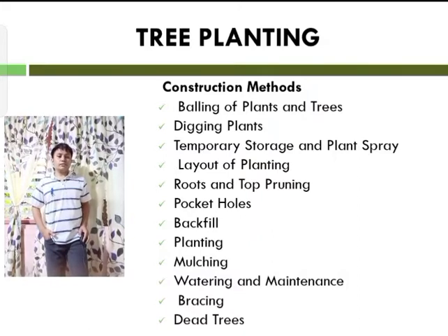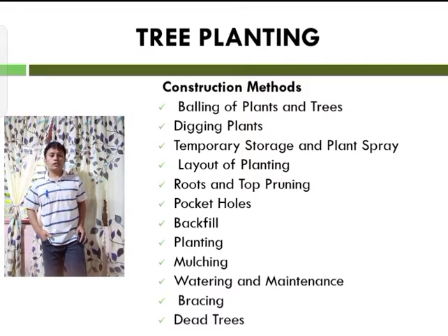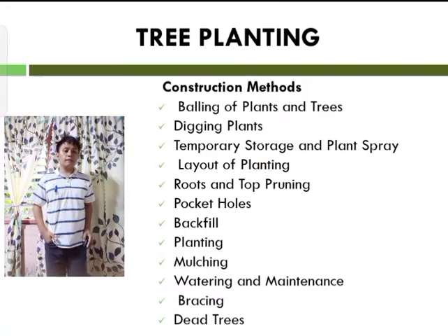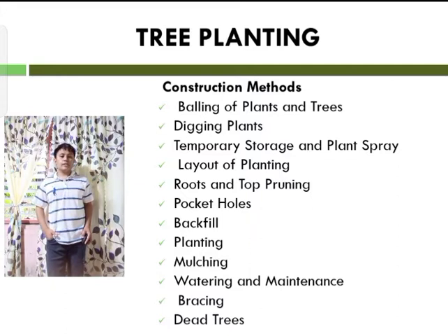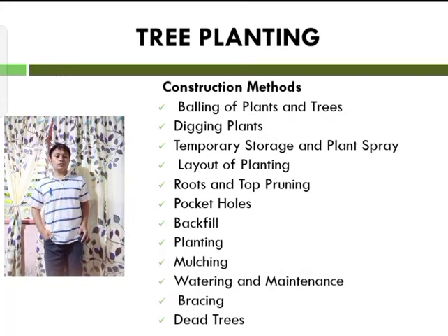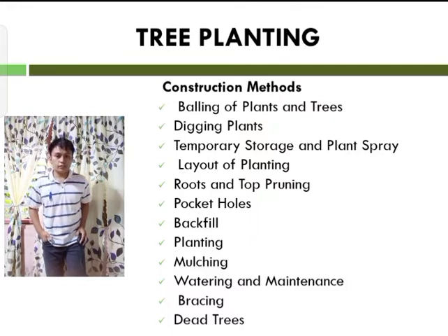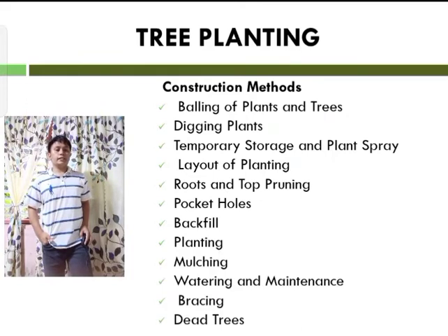So for balling of plants and trees, balling is employed in plants and trees to be transplanted and transferred. To ball out the trees, the depth to which the root system reaches is first determined. So for digging plants, all plants, nursery grown or collected, shall be dug with care and skill immediately before shipping, avoiding all possible injury to the plants, loss or damage of roots, with particular attention being given to the roots in this respect. After plants are dug, their roots shall not be permitted to dry out. They shall not be exposed to hot temperature, and all plants shall be dug in dormant state and shall be held until planted.